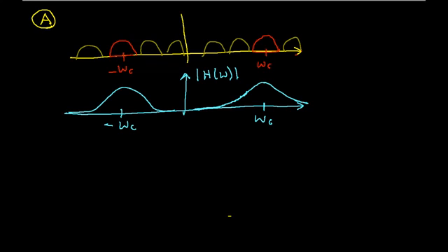So this bandpass filter does get rid of frequencies that are not at omega c, but it doesn't do it very effectively. The reason for this is that it's tunable, and so you can change the center of the passband to the frequency of the station you want to listen to. It's quite difficult and somewhat expensive to create a filter that is both tunable and has a very sharp cutoff frequency. So especially if you're building a cheap AM radio, you don't want to do it that way. And so in the RF amplifier, we opt for tunable, and we'll clean up the spectrum later.